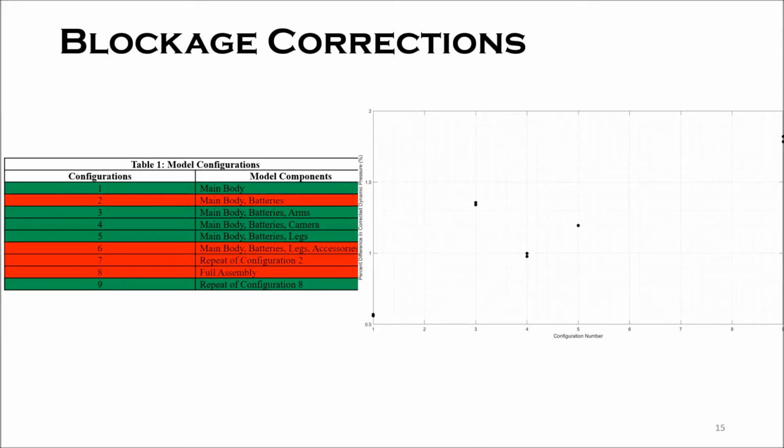And here are the final blockage correction results. The corrections were applied to an angle of attack range of -10 degrees to +10 degrees. This is because, as discussed earlier, wake blockage is affected by the frontal area of the model. The effective model area faced by the airflow changes for greater ranges of angle of attack, and the percent error in corrected dynamic pressure was found to be very large.